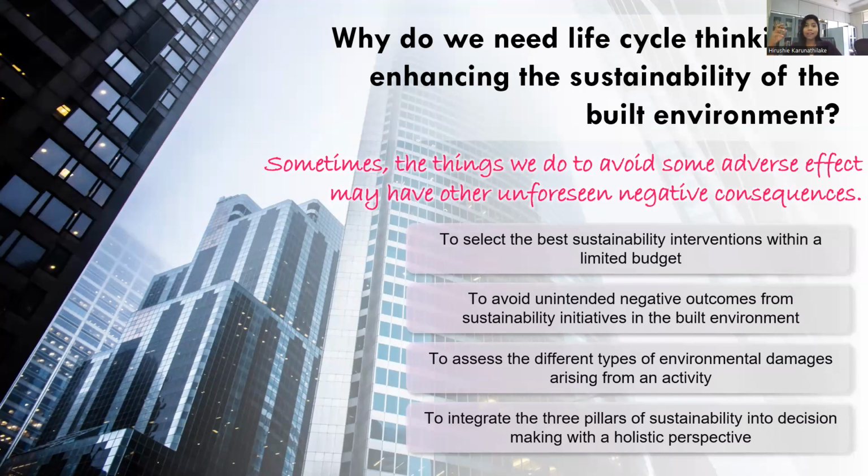In cold climates, insulation is integrated into the building envelope so that we can reduce the thermal energy requirement, so that the heat within the building is not lost to the cold outside environment. By using insulation, we can reduce the energy used for space heating. So far, so good. We are reducing energy use and therefore greenhouse gas emissions.